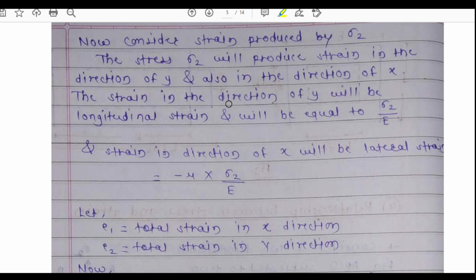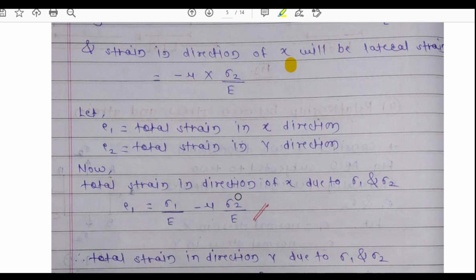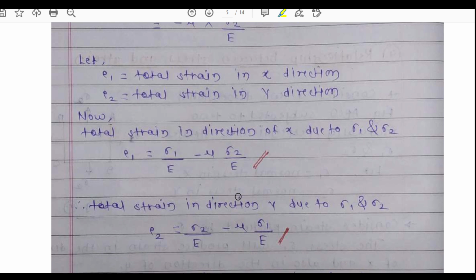Here the longitudinal strain in the y direction is sigma 2 upon E, and the lateral strain in the x direction is minus mu into sigma 2 upon E.